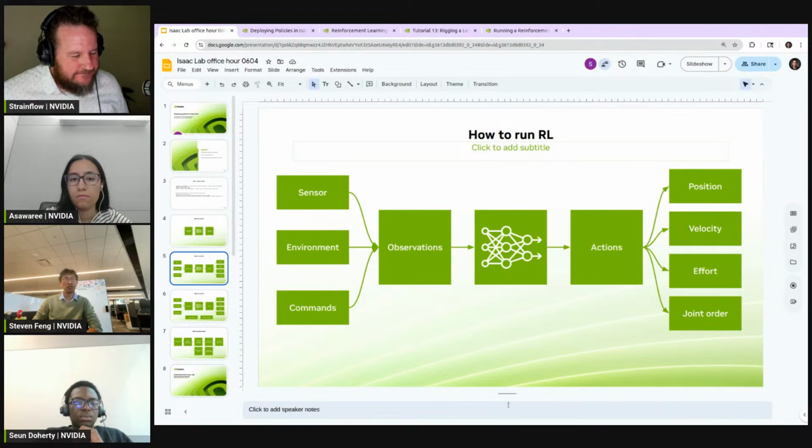When we're running the ROS example for deploying policies, which will be released in Isaac Sim 5.0, we also try to mimic the real-life behavior as much as possible by using simulated IMUs. And we realized that putting the IMU in the wrong position or wrong orientation can have a big impact on how the policy ends up running. So a lot of that frame transformation and making sure data matches is critical for running your policy and deploying it into real deployment.